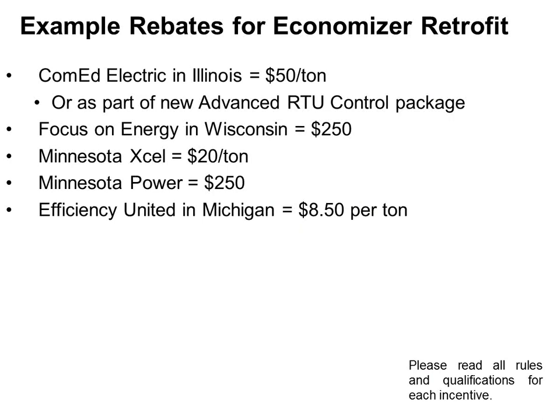Dave types in a question. Does the discharge economizer sensor drive the damper wide open when the compressor and outdoor damper run together? Okay, so once we ask for economizer cooling, the damper modulates solely to maintain the temperature that's typically installed in the mixed air temperature cabinet. Sometimes guys do put it in the discharge position, but typically it's in the mixed air position, and you can tell the economizer controller which one you installed. He's trying to maintain that specific temperature. So I mount it in the mixed air. I'm trying to maintain typically 53-degree discharge air, and I'll keep modulating my damper open until I get 53-degree air. And then the compressor gets kicked on based on the thermostat calling for it. So hopefully that answers his question.